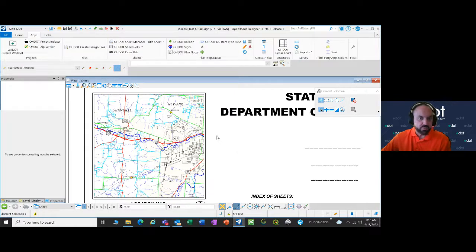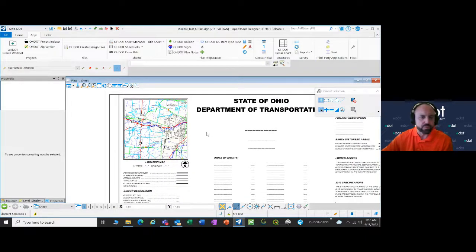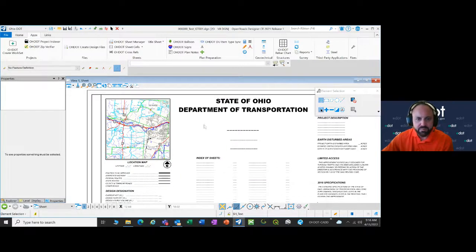So if you want to do detour maps, you could just reference that statemap.dgn into your detour map, and then move it around wherever you need it, and then you could do a clip boundary or whatever for your views for your detour map, and use it that way as well. That way you're not working with 88 different counties. Now you've just got one state map for the whole infrastructure. All right.